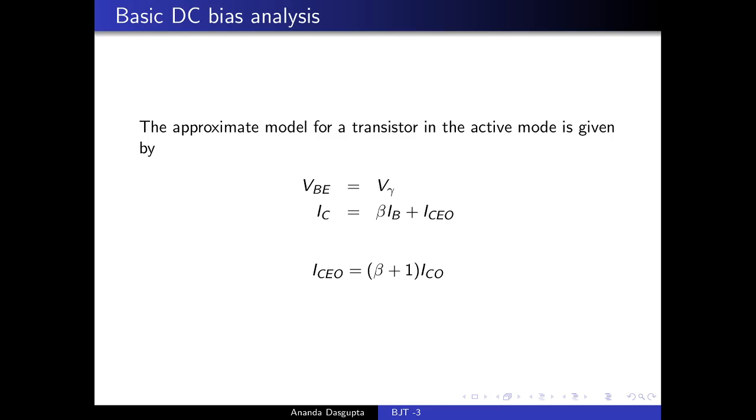Even more disastrously, this increased current in the collector would give rise to higher heating that might produce a further temperature rise, which would perhaps lead to an even bigger rise in ICO, causing again a further temperature rise, and so on, and the whole thing might snowball, and you may have what is called thermal runaway, and your transistor may get destroyed. So, circuits where IC changes rather rapidly compared to ICO as temperature rises, even if the change is very small, for them temperature rise may become quite a big problem.